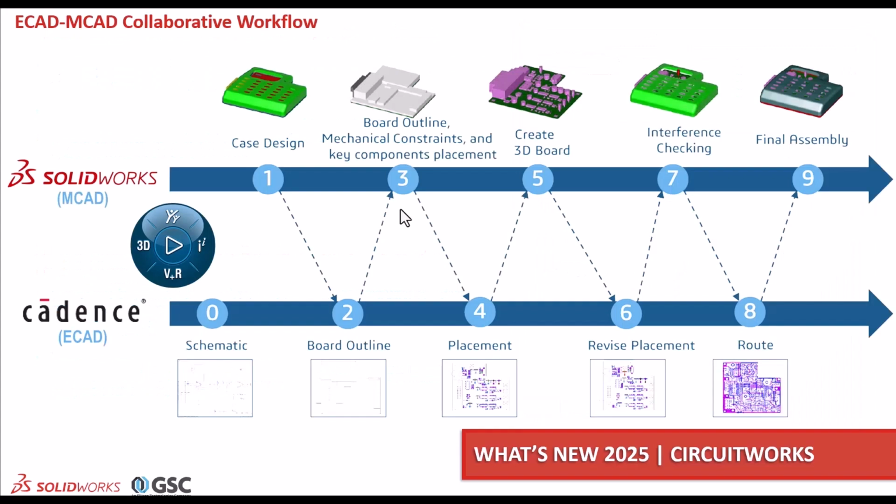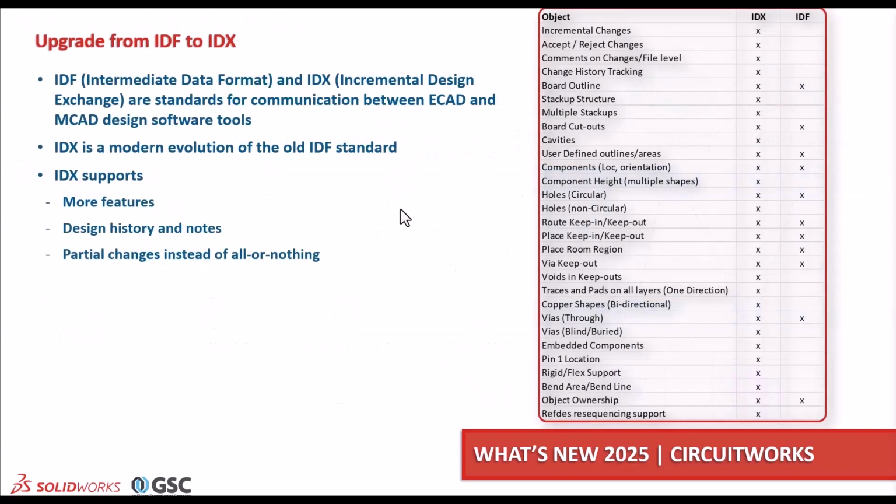So why have this integration? Well, the circuit board portion of so many products is just assumed at this point. So this ECAD, MCAD workflow, sending and transmitting your changes and change requests back and forth, making sure everything fits, functions, and works the way that you need it to, is paramount in product design. The file format, as they have added this IDX3 format, has a lot more granularity to it and a lot more design information stored in that file type. So as you push and pull your changes, you'll be able to select or reject the individual portions of those changes instead of just all or nothing.